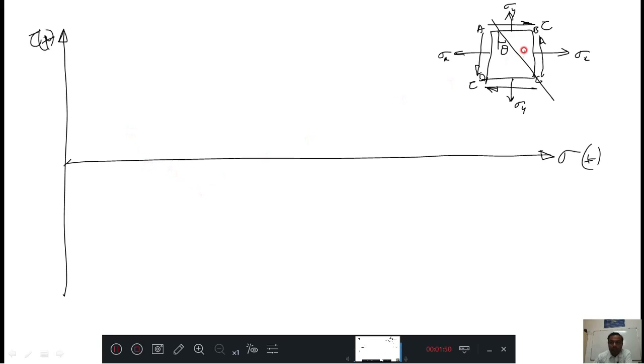Now what we need to do, here the conventional diagram is there. Stresses sigma x, sigma y, and tau are acting, and there is one plane of interest making an angle theta with the vertical. On that, stresses sigma theta and tau theta will be generated. Analytically we know their meaning, but how to draw them graphically? First, this is a normal stress, so whatever the normal stress is, you need to mark it here. Yes, I marked it. This distance is sigma x.